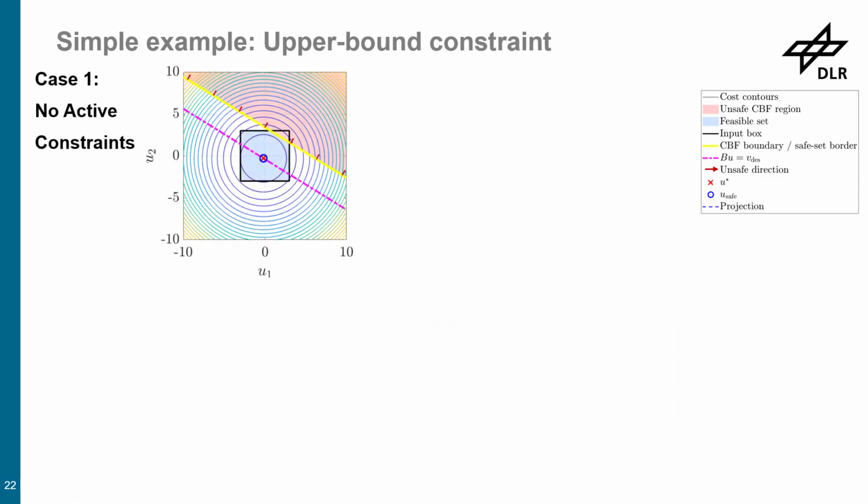So if you have a 2D case, and you're having a tau or a moment command on one axis, what you actually obtain is this magenta line. This magenta line is a line on which all the solutions for the commanded moment are lying. So any point on this line will solve your problem. But again, you have the cost function, and you try to minimize the cost function. So normally, if possible, you search for a solution which is right here at the center, 0.